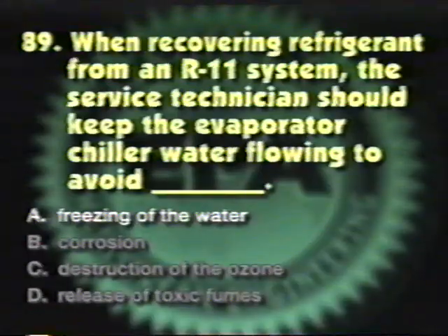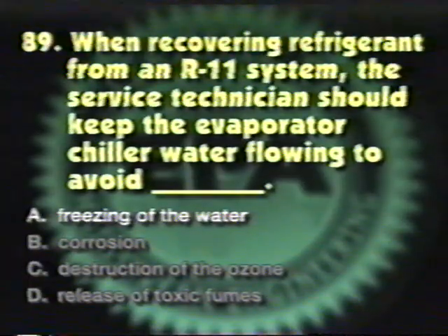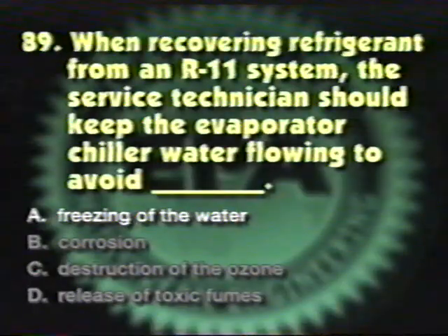The answer here is A. Water must be circulated through a chiller during refrigerant evacuation to prevent freezing of the water in the evaporator heat exchanger.